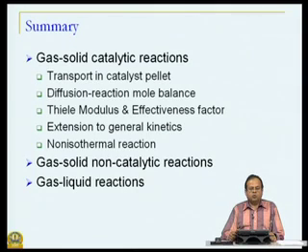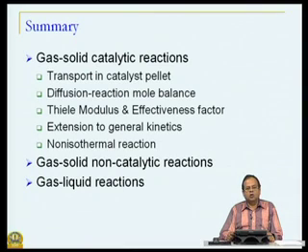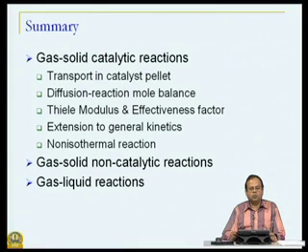So, this transport process will also play a crucial role in determining the kinetics of the reaction. Now, how does this transport process occur? We have diffusion in the bulk phases, but when it comes to the catalyst pores, which can be of micron sizes or even smaller, there are other factors such as Knudsen diffusion and viscous flow, that is capillary flow, which also come into the picture.